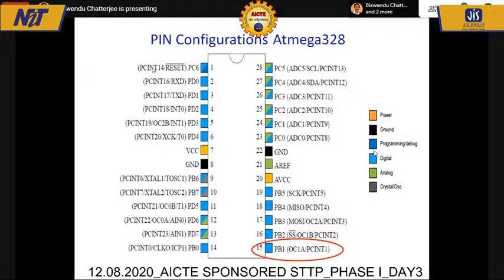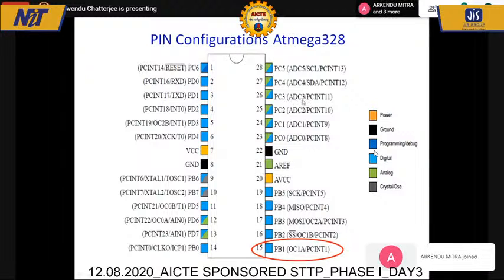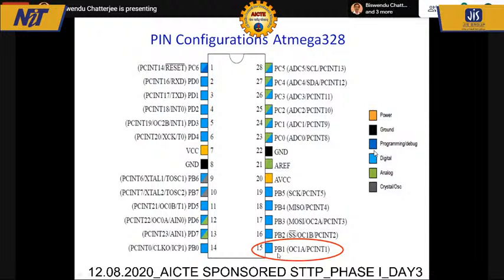Now come to the hardware part. Recapitulate this IC pin, I have told you these pins perform several other functions. For example, PC3 can also perform as ADC3. In this way, if you look at this PB1, port B1, it can perform as OC1A also. Now look, this pulse width modulation is an output.